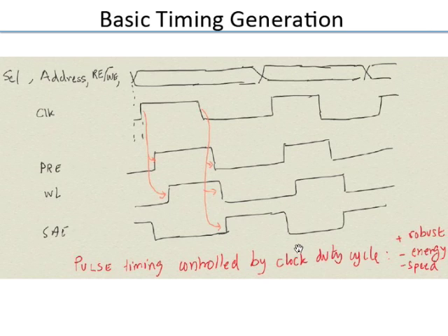So with a scheme like this, you have two edges. The rising edge does something, the falling edge does the other thing. So by controlling the spacing of the rising and falling edges, you can separate out the two. Controlling the spacing of the two could be done basically by slowing down the clock. You slow down the clock, and if you keep the same duty cycle, that is the percentage of time the clock is high or low, everything scales, and so you can get it to work. So it's a safe, robust approach, but it's not very efficient from an energy and speed perspective. It works, but if you want to really push speeds and reduce energy some more, you have to do something more.